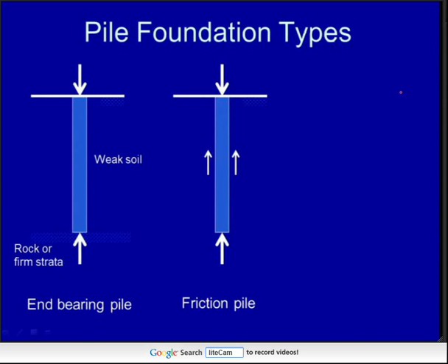So it's about communicating the idea that, in this case, the end bearing is the important mode of pile support. In this case, it's shaft friction. So the construction team makes sensible decisions when trying to get the piles into the ground. And it's a feature of construction that the job isn't easy. You have to make a lot of decisions on site as you go in order to make it buildable. And what you want as a designer is for those decisions to be compatible with your design.